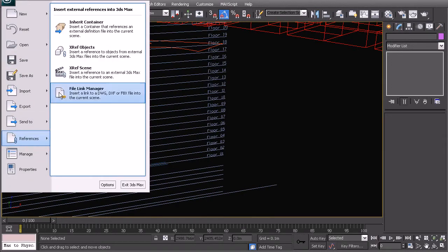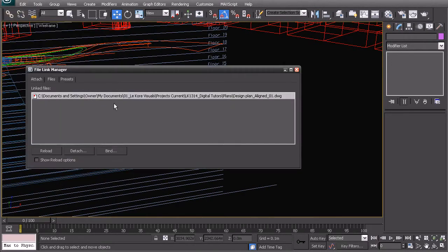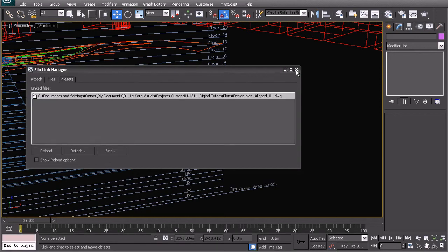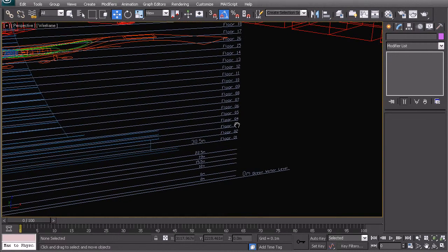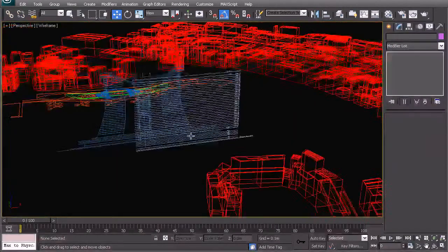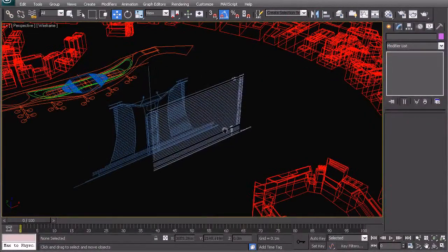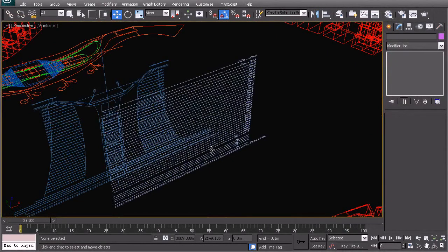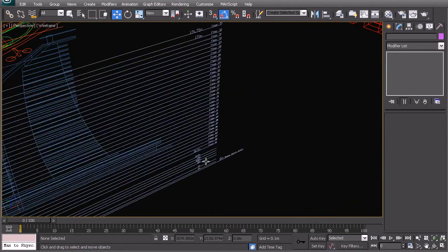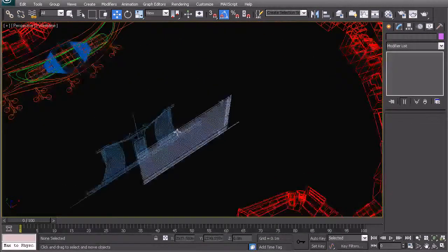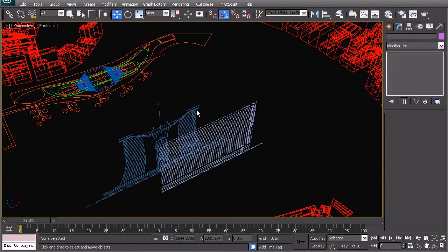And you'll see this is a trial and error process, and it just goes to show how easy it is to go back and forth between AutoCAD and 3D Max and then update these details. The beauty of it is that all of this has already been rotated and in place, so I don't have to now re-import, re-rotate, realign. It all just comes into the correct location, even though I've added brand new data on the AutoCAD side of things. So that is a really fantastic tool that you will end up using all the time.